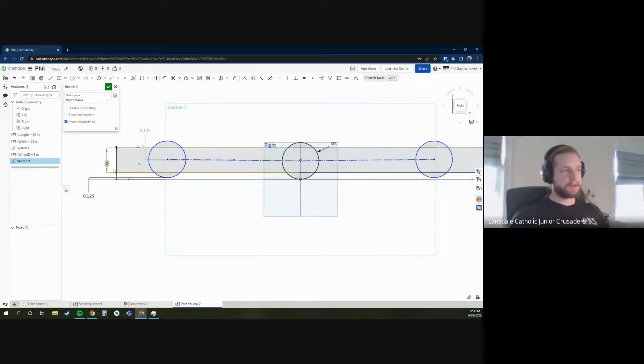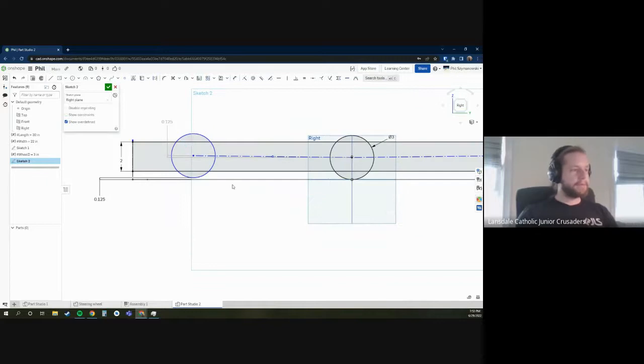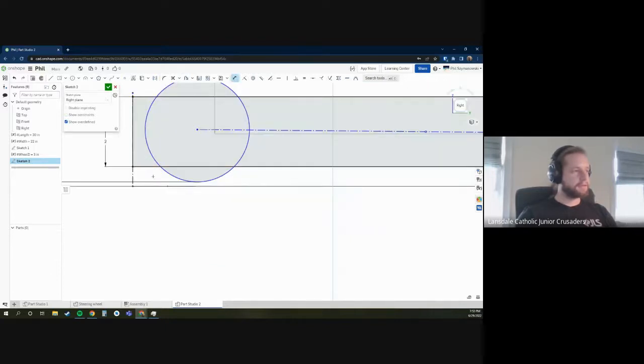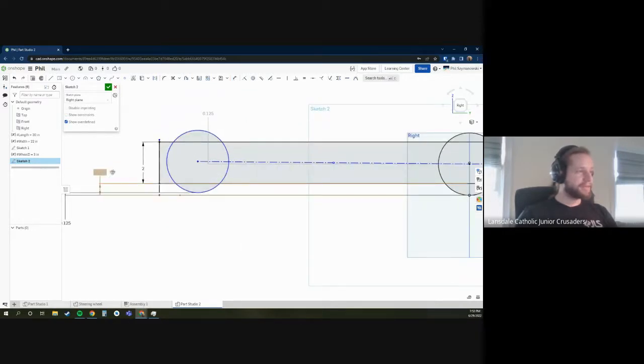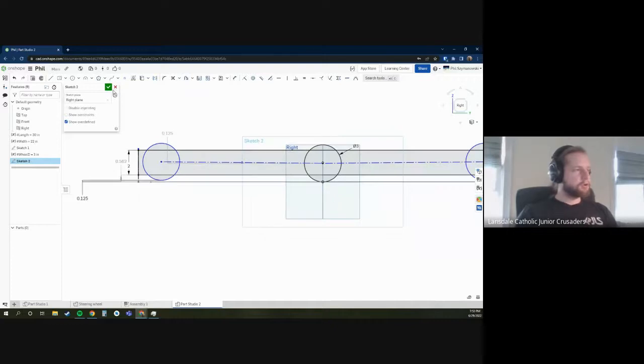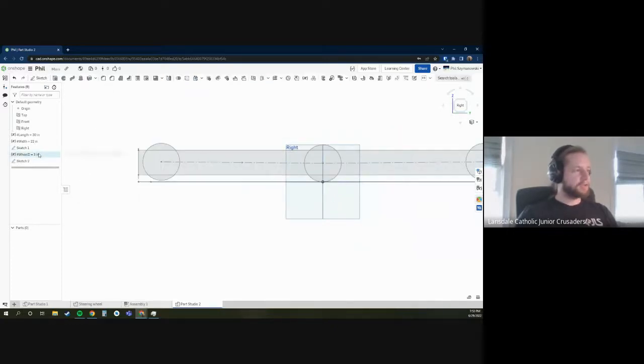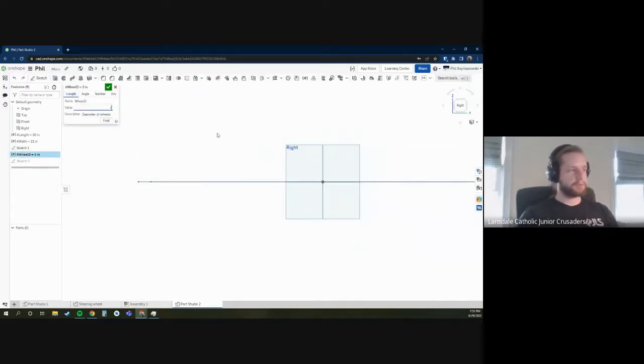And now we've got the height of our tubing, of our drive rail. Maybe it seems like we don't have a whole lot of ground clearance here for our wheels. Like, what is that? That's not very much from here to here. The bottom of the 2x1 to the floor, we only have just over 1/2 inch of ground clearance. That's not a lot of ground clearance. So maybe 3-inch wheels aren't going to do it. Maybe we have to skip the 4-inch wheels.